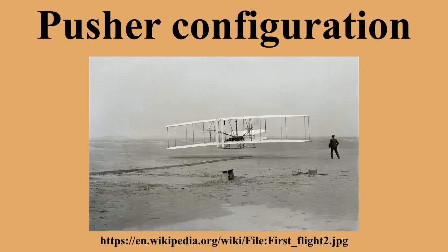By the late 1930s, the widespread adoption of all-metal stressed-skin construction of aircraft meant, at least in theory, that the aerodynamic penalties that had limited the performance of pushers were reduced. However, any improvement that boosts pusher performance also boosts the performance of conventional aircraft, and pushers remained a rarity in operational service, so the gap was narrowed but was not closed entirely.